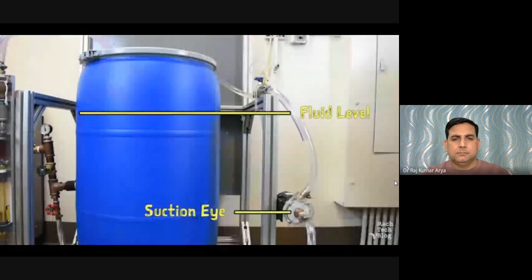If the pump is ever starved of fluid, certainly the pump's performance will be affected, but it's actually more serious than that. It's possible that the pressure at the suction eye of the impeller will drop below the vapor pressure of the pumped fluid. If that happens, then the fluid will effectively boil. Little bubbles will form, travel partway through the impeller, and then collapse at supersonic speeds like little bullets, taking bits of the impeller along with it. This is a condition known as cavitation, and a pump that's experiencing cavitation is not long for this world.